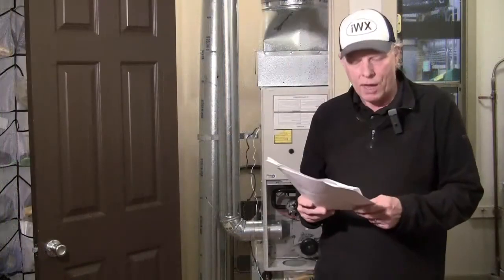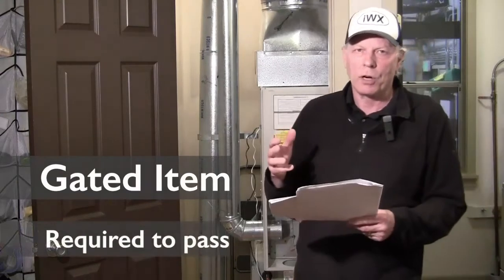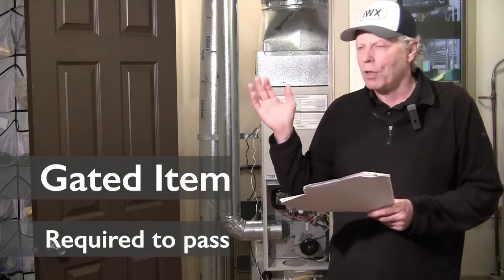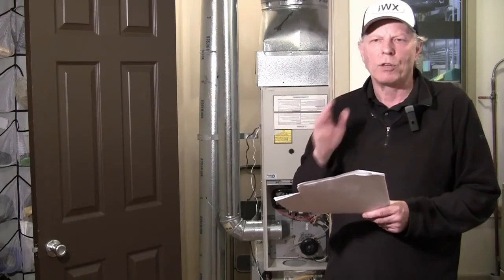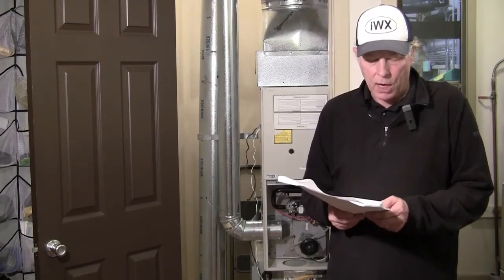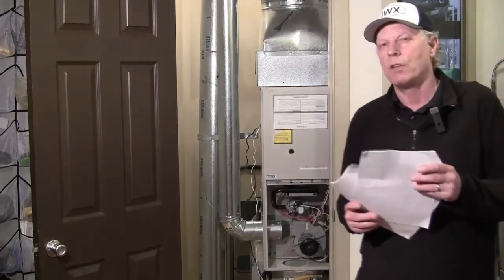Okay, we're on line 7, and line 7 is a gated item. And as we talked about earlier, gated items are super important. You have to get them correct. The proctor won't tell you whether you get anything right or wrong along the way, but if you don't get this one correct, you'll fail the entire exam no matter what you've done the rest of the time. So it says candidate monitored and stated ambient CO levels measured in the CAS during entire combustion safety testing.